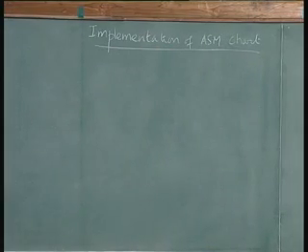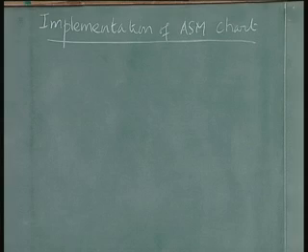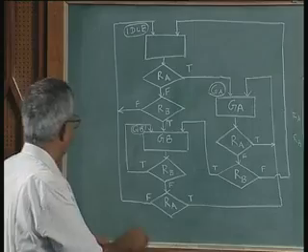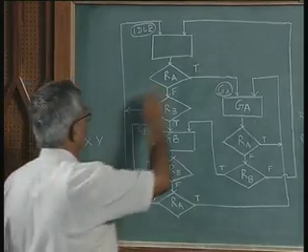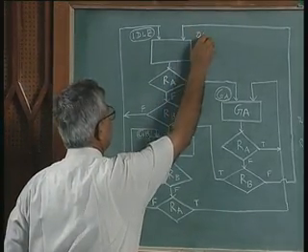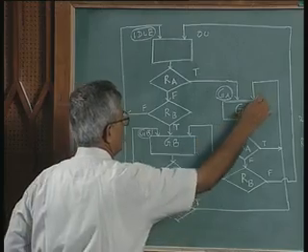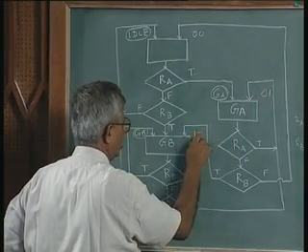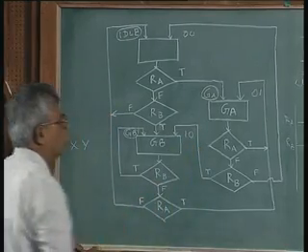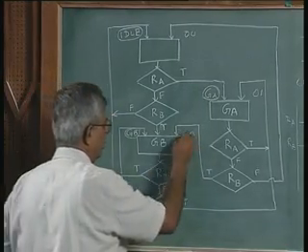Before we do that, we have to assign states, same logic or same concept as the state graph. There are 3 states, so you need 2 state variables. We will call them x and y because A and B have been used here. I will arbitrarily assign the state 0 0 for this, 0 1 for this, and 1 0 for this, or 1 1, does not matter.